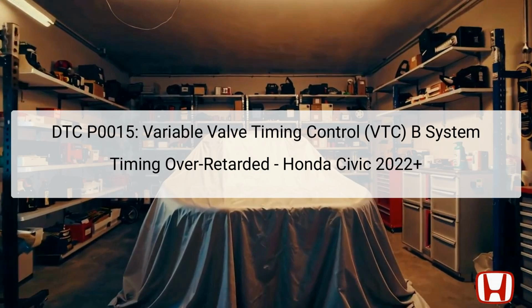When the exhaust camshaft phase angle shifts beyond the prescribed limits, the Powertrain Control Module, PCM, identifies a malfunction and records the fault code. Understanding the components involved is essential, namely the VTC Oil Control Solenoid Valve B and VTC Actuator B, which directly influence this timing mechanism. Their malfunction can lead to significant changes in engine performance, potentially affecting everything from fuel consumption to emissions. Therefore, addressing the P0015 error immediately is crucial for optimal vehicle functionality.